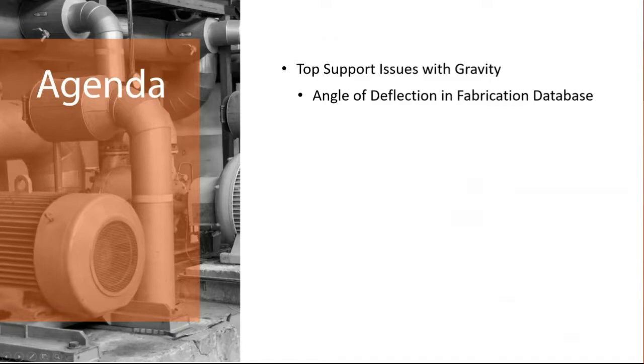The other feature that we want to get into is placing a point on a floor drain. We're not going to do it on a floor drain. Actually, we're going to do it on a storm drain, but it's going to be the same process of adding a point to a family and then using that family to capture points for your total station. So we'll go through that process.